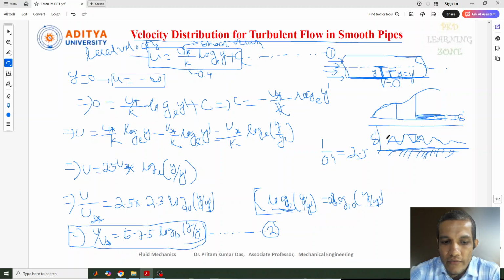the velocity distribution in the laminar sublayer, as we have seen, is parabolic in nature. And let me inform you of one more thing. What value did we get here? y equal to y dash. That means the curve will not start from the origin, not from this point. It will start from here. Which nature? The parabolic nature, because if you have seen it for a pipe,